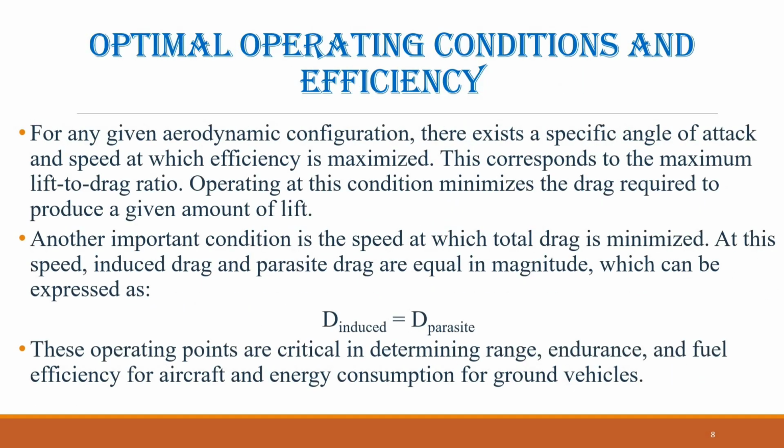Optimal operating conditions and efficiency. For any given aerodynamic configuration, there exists a specific angle of attack and speed at which efficiency is maximized. This corresponds to the maximum lift-to-drag ratio. Operating at this condition minimizes the drag required to produce a given amount of lift.